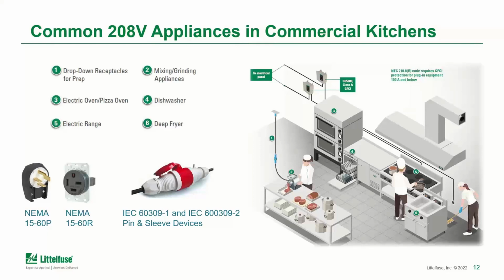When you do that moving of the equipment around and connect it with plug-in cord, that's where those GFCI requirements come into play. And that's specifically because flexible cords are prone to wear and tear over time as you're moving it around, and that worn insulation really does increase the worker's risk for electric shock.